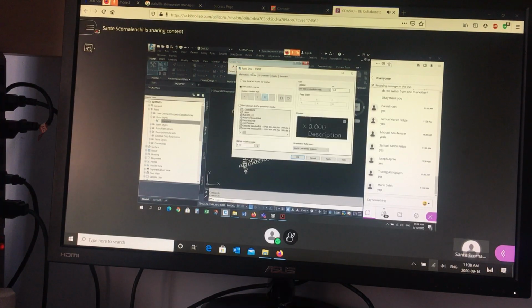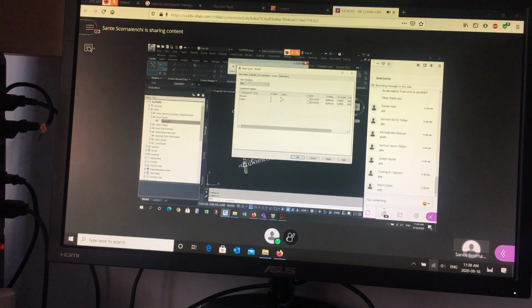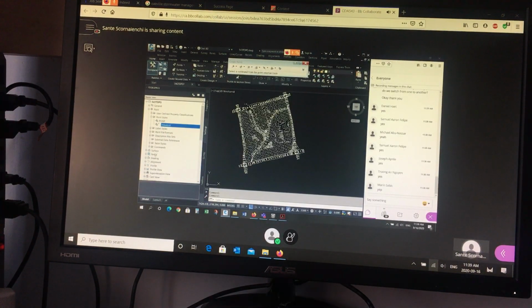The marker, well, you can use an AutoCAD marker, you can use a custom marker, or you can use a block. Those are the 3 different things. I'm going to use a custom marker for this one. I want the absolute size to be 0.5, and in the Display tab, I want to make sure everything is on layer 0 and color by layer. So the settings that I've asked you for are mostly the default settings. And when I say OK, well, now you have 2 styles.